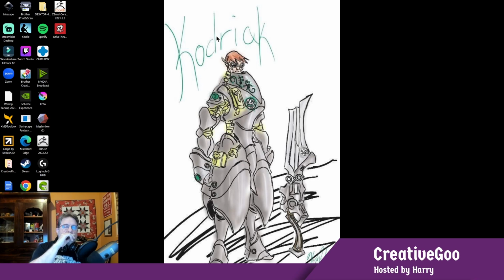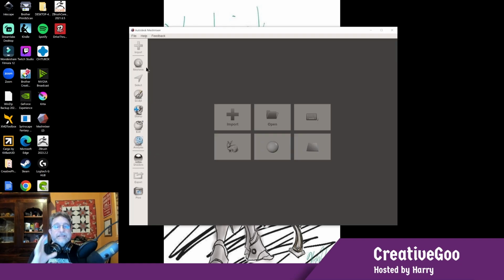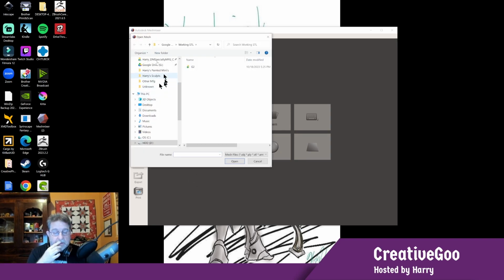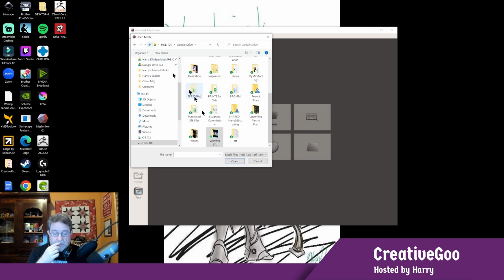So what I'm going to show you guys is another piece of software I use. It's called Mesh Mixer. You can use it to manipulate STL files and do some 3D modeling. I use it because it can check the integrity of my model. So no matter how good a job I do in ZBrush, there are still going to be problems potentially. Sometimes it works great, the magic works, and I can just print it. Most of the time, however, there are still problems with the model, and Mesh Mixer finds them for me. So let me go to where I was just at.